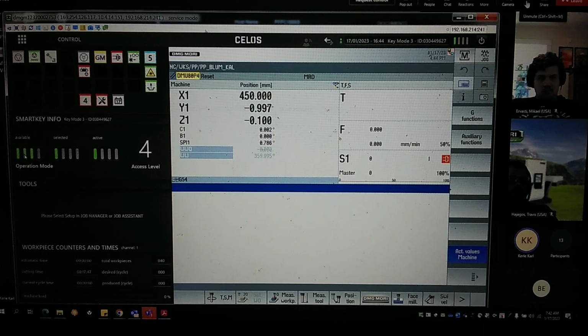We have a different speed limitation valid here. That means it's only 2 meters maximum jog, depending on the production date of the machine. Also, you can have 4 meters, but that's old. And no rapid speed, no program run, no automatic function is able to start. No tool change, no pallet change, no spindle speed, nothing like that. Okay?